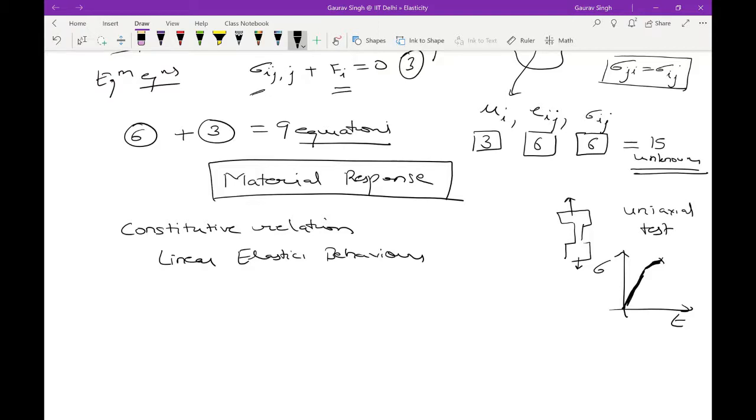But if you take it further than this, then if you release the load, it will come back to say this place, which is not zero strain. So that's the elastic limit. Proportional limit, as has been told, is the place where this linear elasticity works, and beyond this, the linear proportionality between stress and strain ends. For most materials, the difference between elastic limit and proportional limit is negligible, and hence you will find only one of them reported, and they are interchangeably taken. But you should know the difference between the two.